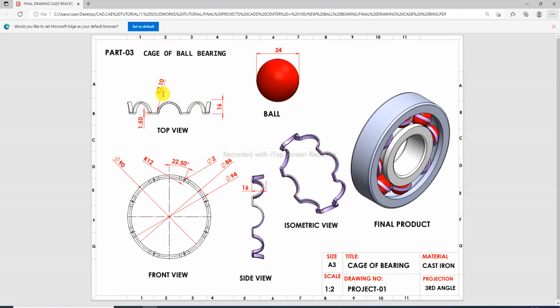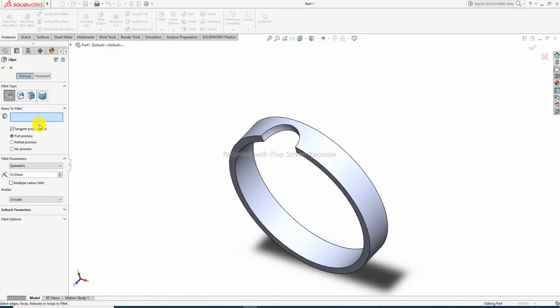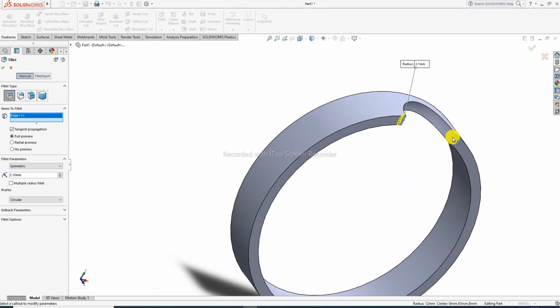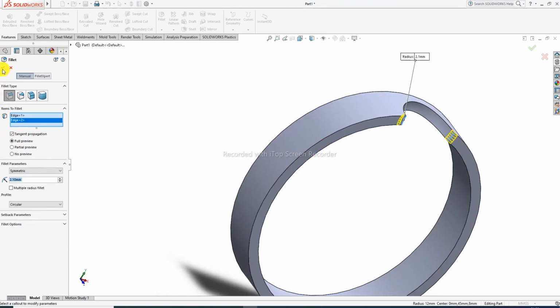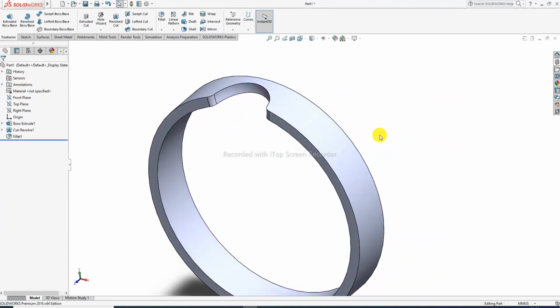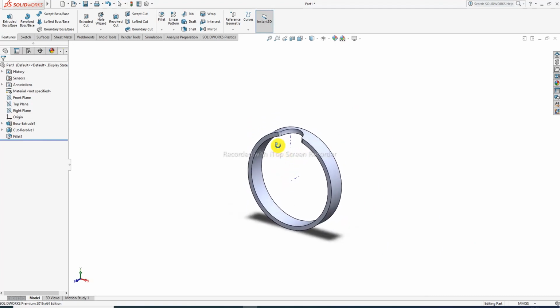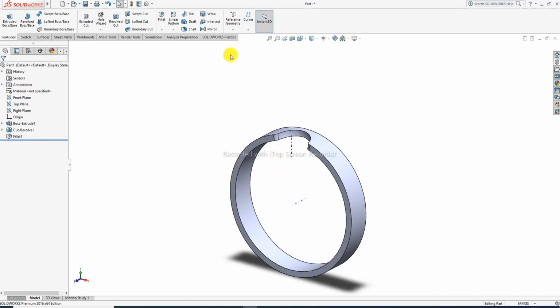And the fillet, you can see here, the fillet radius is 2.1, and the shell command uses 1.5. Okay, radius is 2.1. This point is a fillet, and this point is a fillet. Okay, and select this temporary axis, and select Mirror, Circular Pattern.